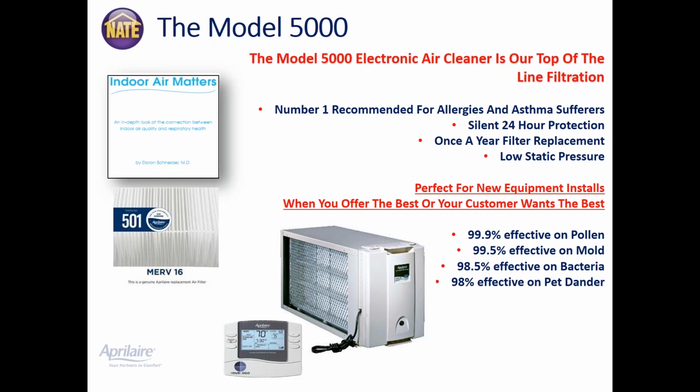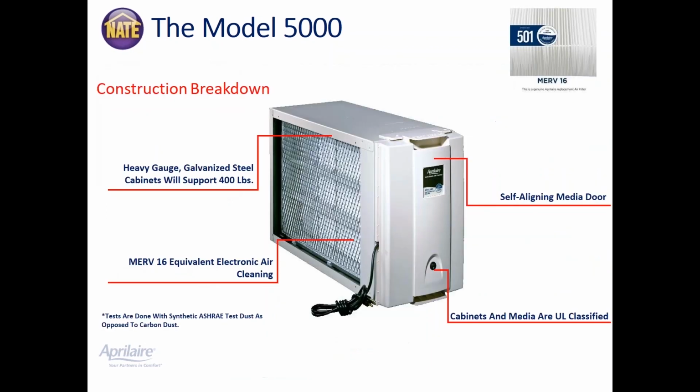So now we offer a true MERV 16 media filter, which has a slightly higher static pressure, of course, because you're using a MERV 16 media. But we also offer the Model 5000, which is an electronic air cleaner, which gets you approximately a MERV 16 performance. Again, you can't do the MERV test because of the electronics. That's true with anybody's electronic air cleaner. But when we look at the efficiency at trapping at different percentages and sizes, it would fall into that MERV 16 category with a much lower pressure drop. So 2 options.